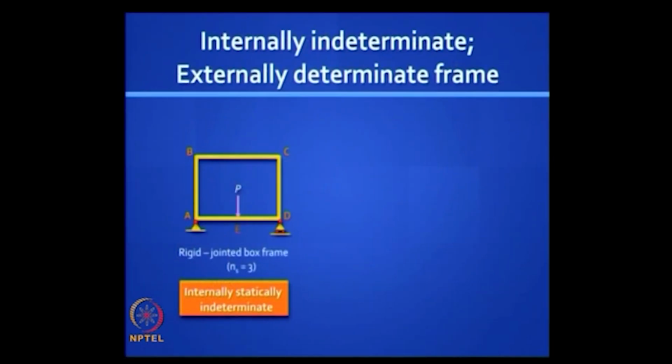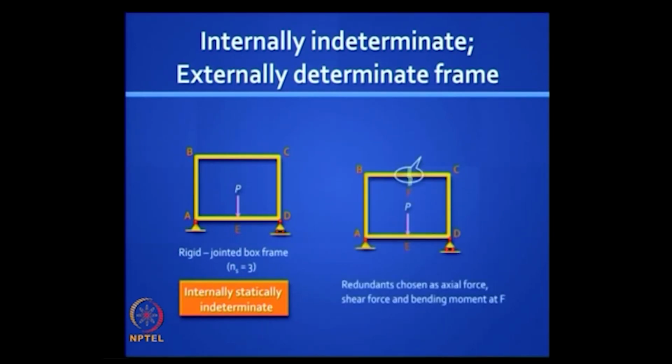But there are some other types of problems, for example this, where the support reactions are very well known, it is externally statically determinate. Here the indeterminacy is internal, and if you put a cut anywhere, you will expose a shear force, an axial force, and a bending moment, and you have to apply them equal and opposite as shown here, right.